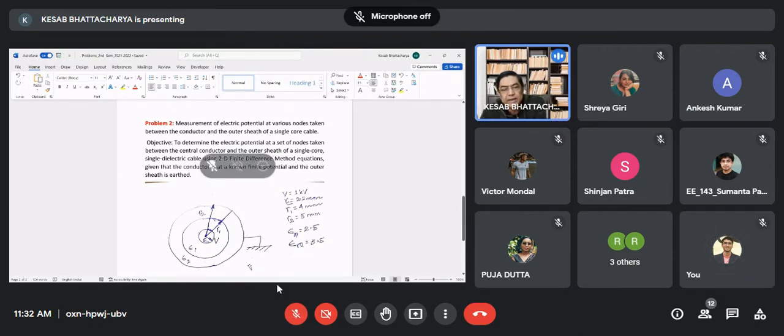Yes. So the result will be a trapezium. There you just find out the nodes on the boundaries. The nodes lying on the outermost boundary will be held at zero potential. The nodes lying on the conductor surface will be held at, sorry, 1 kV as per our problem. And for the nodes lying on the two side boundaries, you have to calculate the potential.